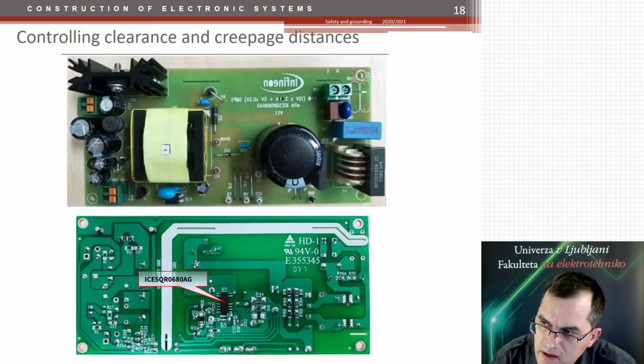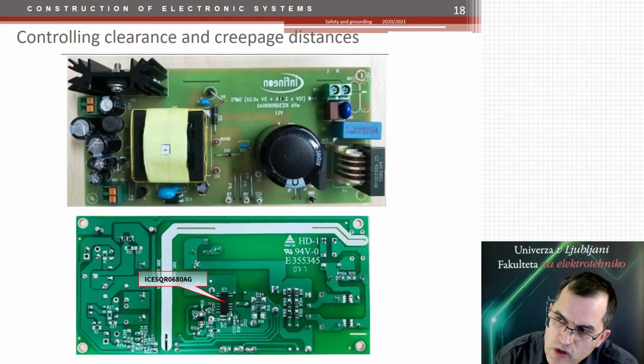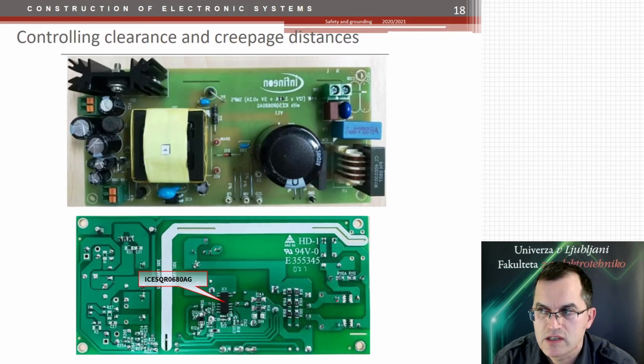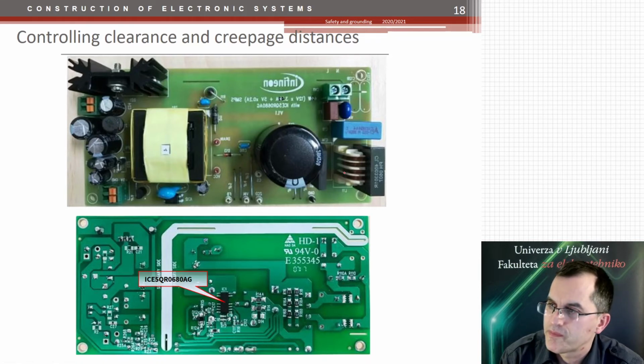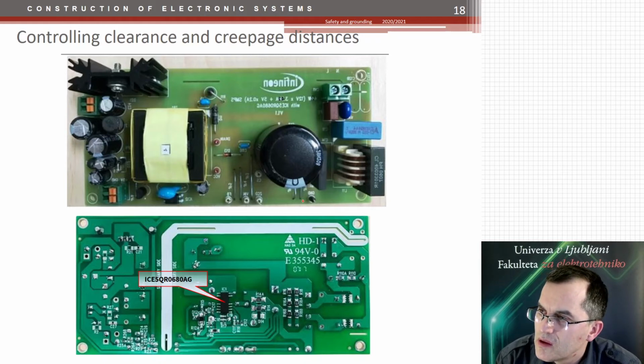These are the structures on the PCB which are acting as high voltage suppressors. In terms of these spikes, these features are defining a breakdown voltage that would limit the voltage spike, so you can have some over-voltage protection by that. These are so-called spark gaps. And then you have the input capacitor, you have the transformer here.